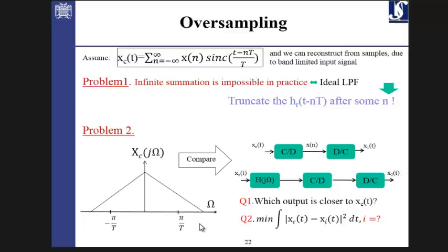When a filter is supposed to be applied to the continuous time domain signal, it means that filter should be implemented in analog form, not digital, using capacitors, inductors, resistors, and so on. So everywhere you hear about the anti-aliasing filter, it's an analog filter. Even if every other analog filter vanishes with time, there is one filter still remaining, and that's the anti-aliasing filter.